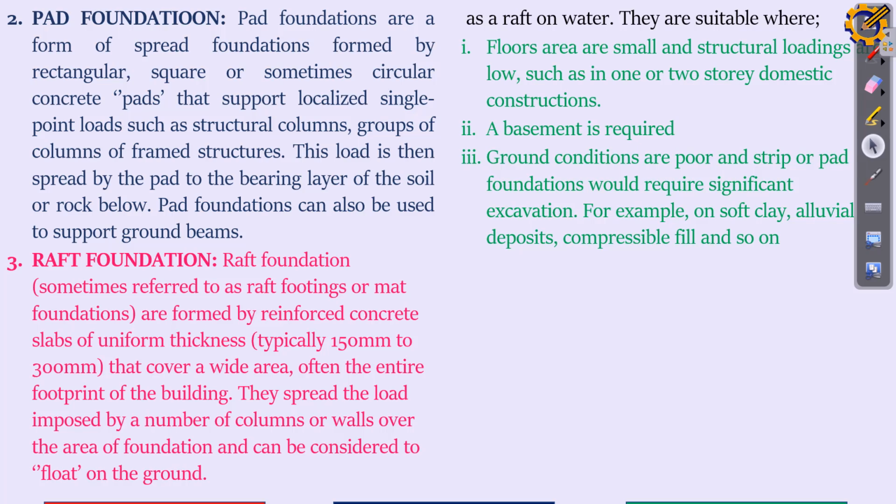Ground conditions are poor and strip or pad foundation requires significant excavation, for example on clay deposits, compressible fill, and so on. In a sandfilled area, this is what they use. They use what? A raft foundation on sandfilled areas.